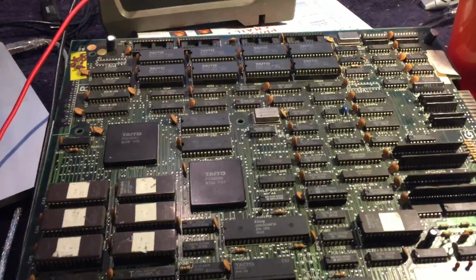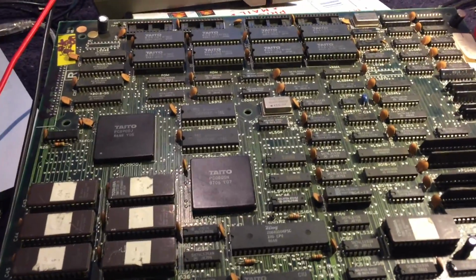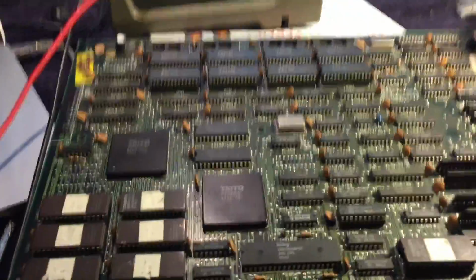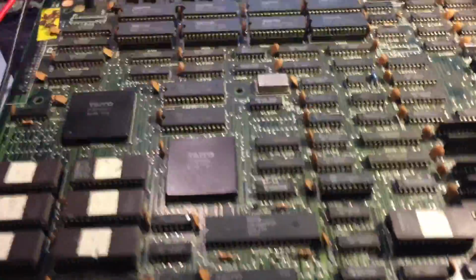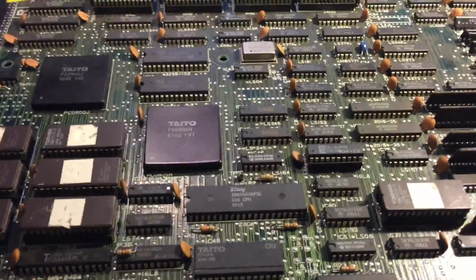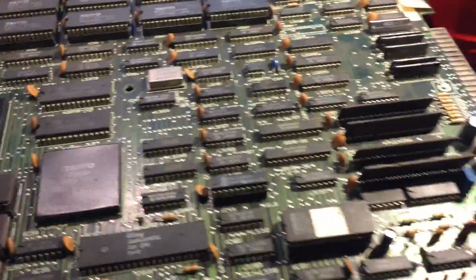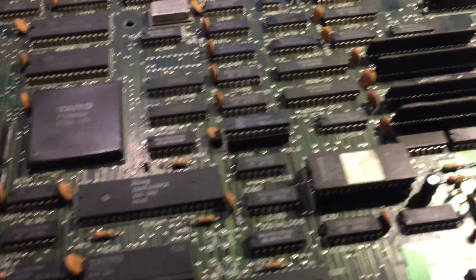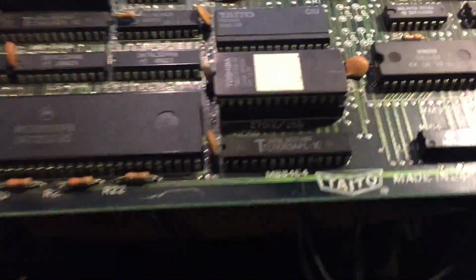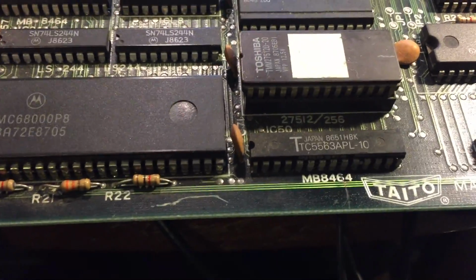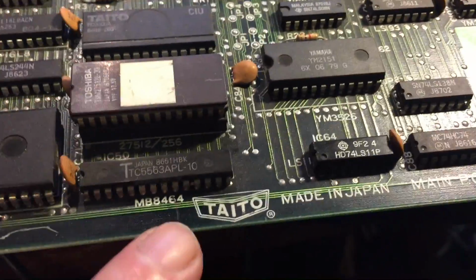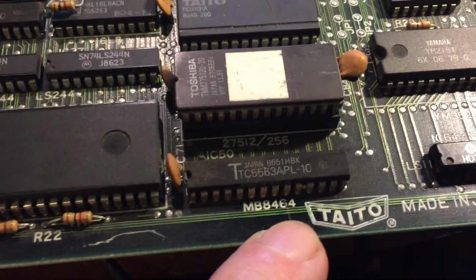Well, I confirmed with my meter that there is indeed a bad connection between that buffer IC and the interconnect IC. So I've been looking around on the board a bit for damage, and I'd noticed a couple of things before, but none of them looked too serious. There's a little tiny scratch right here, but I'm pretty sure those are okay.